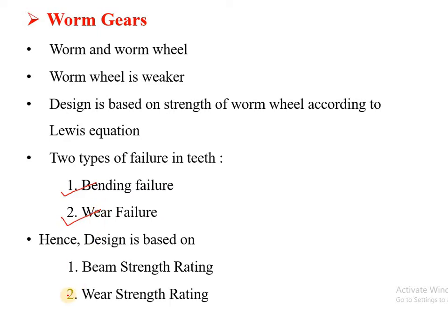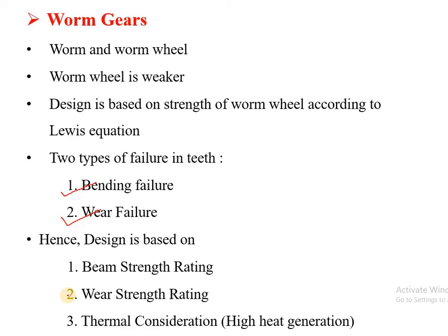And as we know, there is maximum friction in a worm gear drive as compared to other gear drives. So thermal consideration is an important topic to be considered under worm gears while designing, due to its high heat generation.